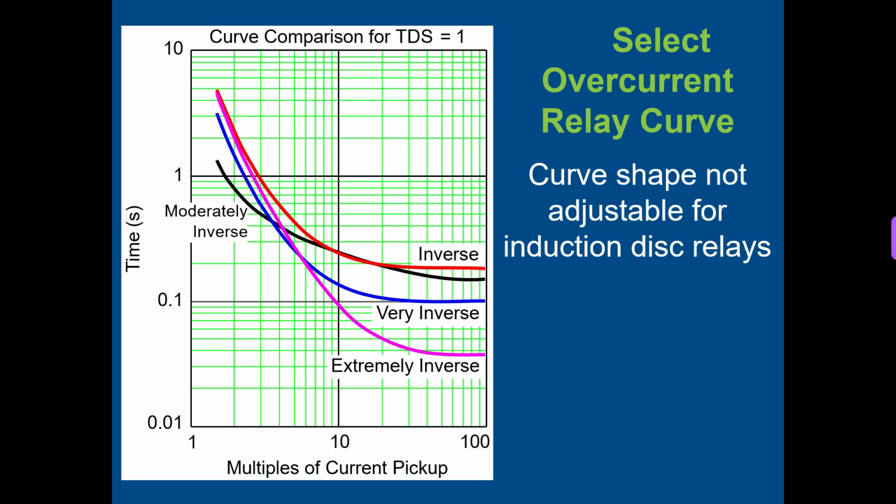We could have a damage curve which doesn't fit any of these overcurrent relay types, and then there is a problem. That's why a modern numerical relay gives you the flexibility to draw a custom characteristic for overcurrent relays. We will discuss this in detail while discussing the implementation of overcurrent earth fault relays through different types of numerical relays.